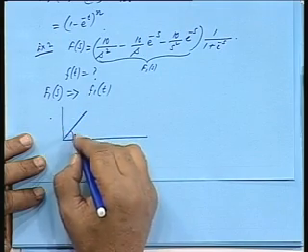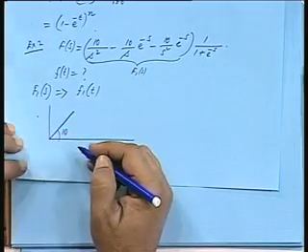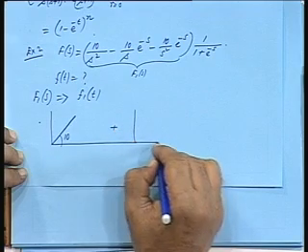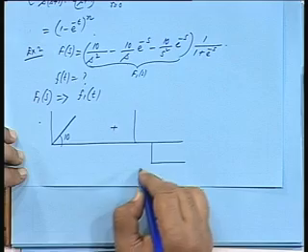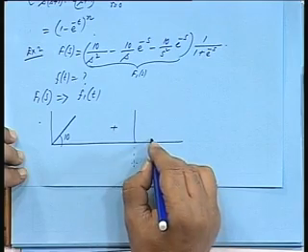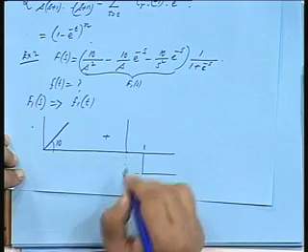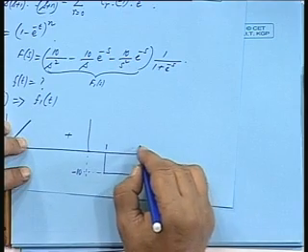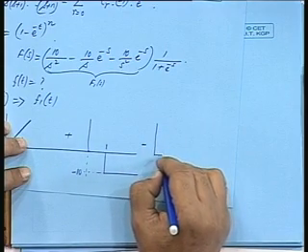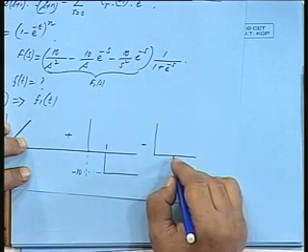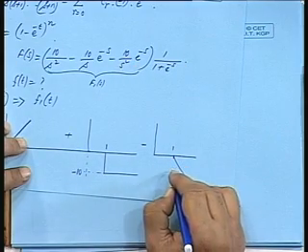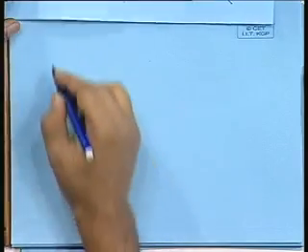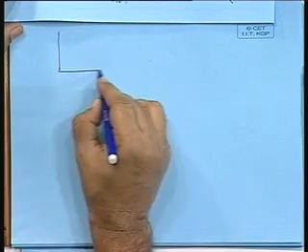of slope 10. I will write slope in terms of this, minus 10 by s. So, 10 by s minus 10 by s, this is with e to the power minus s. So, at 1 second we apply a step of 10 volts, negative step, and then minus 10 by s squared e to the power minus s. So, again at 1 second we apply a slope of minus 10. What is the summation of these three? Summation of these three will be giving me the net value f1(t).